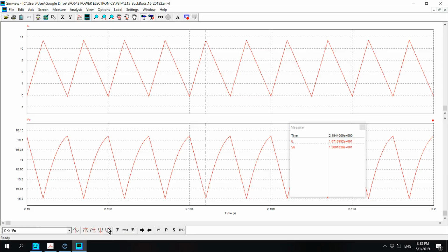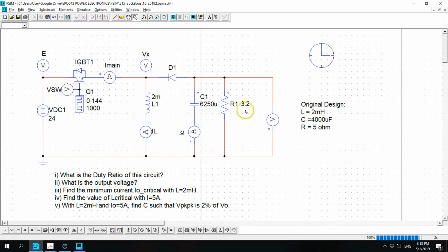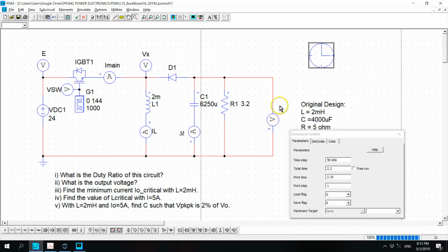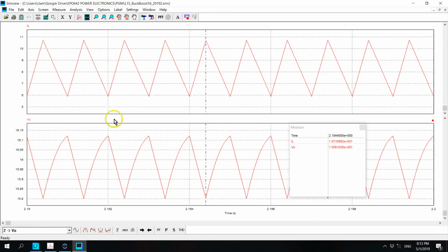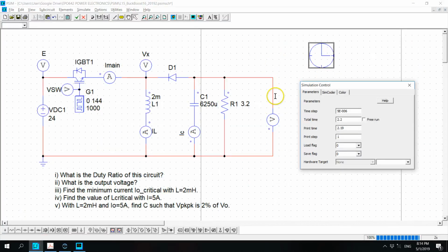So it's quite accurate if you use simulation, and therefore the simulation will help you to confirm your calculations. Yeah. But again and again, you need to simulate it correctly, properly, so that you get a correct waveform. When the waveform gets into its steady state, you can see that it is symmetrical. The inductor current is symmetrical. The output current is symmetrical. Let's say if you simulate it not long enough,